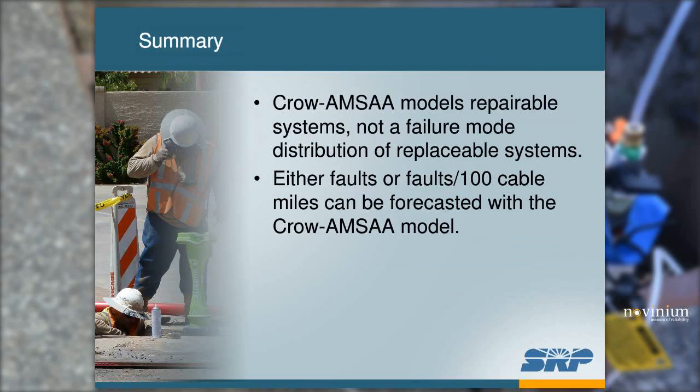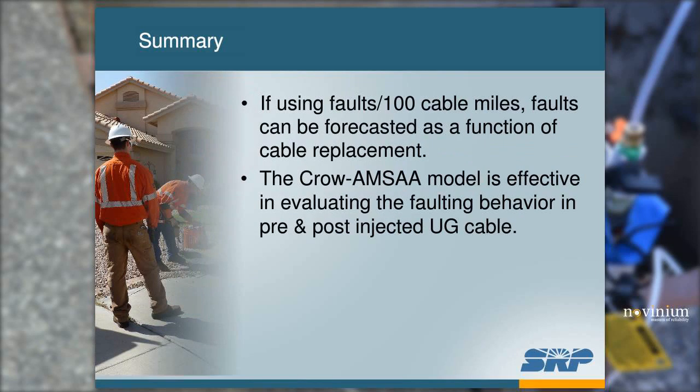So I'd like to summarize everything right now. Again, we use the Crow-AMSAA model for direct buried cable because it models a repairable system and not a failure mode distribution of a replaceable system. It's a fairly flexible model. We can model faults or faults per 100 cable mile. If we use faults per 100 cable mile, then we can forecast faults in terms of cable replacement.